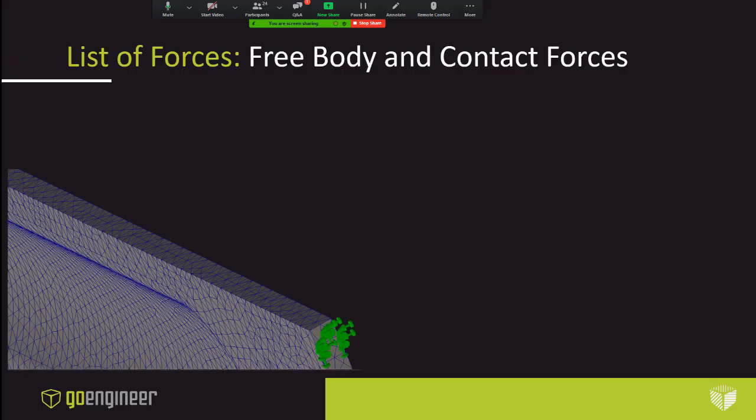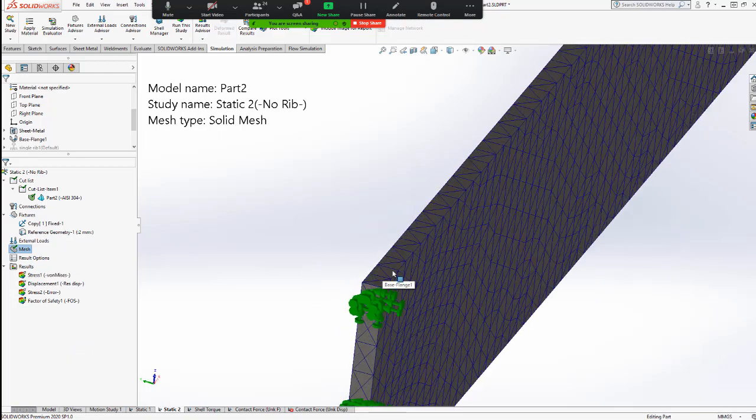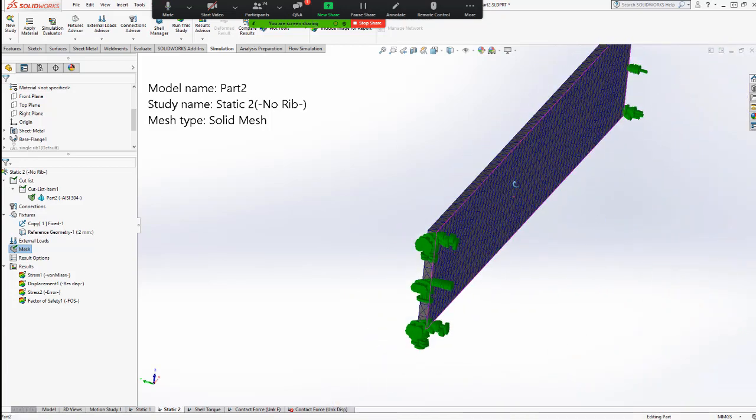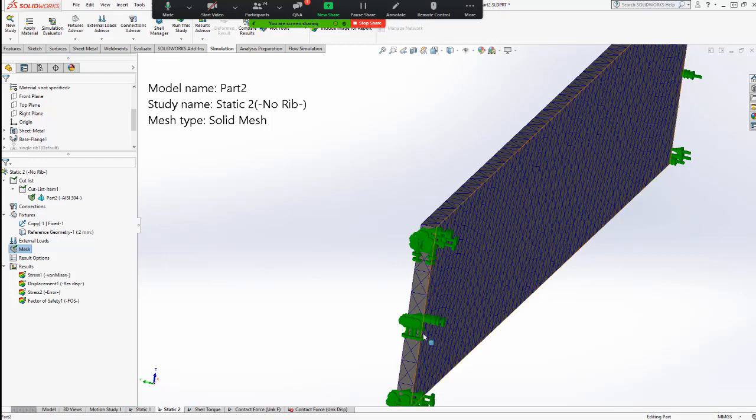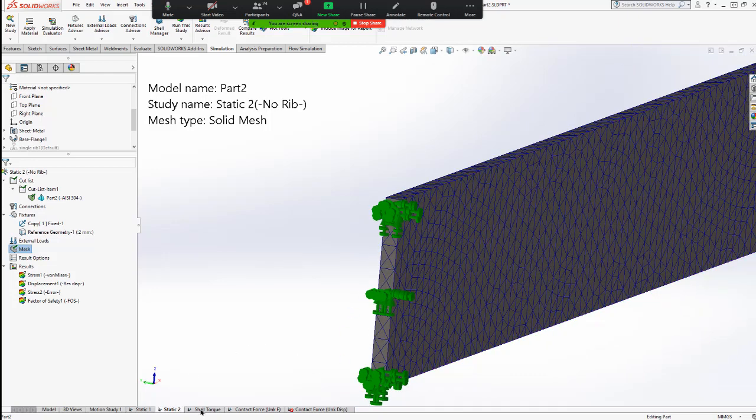Now, since we quickly went over the mesh, I'm going to talk about when we would want to make that a shell. Seeing this mesh is an example of when we would have enough elements that we can argue, okay, we can keep it a solid. But if we have the mesh like I showed you just before, our element density is not there. We don't have 3 elements across this length. So it would actually make sense to assume this as a shell, because it will luckily be fine with this just being assumed to be a thin plate. And I'll show that to you now.